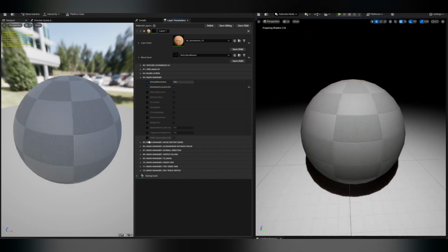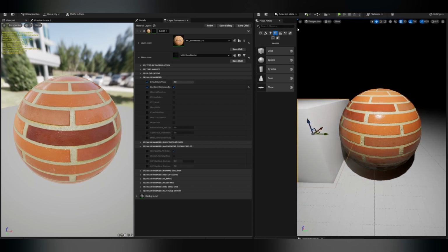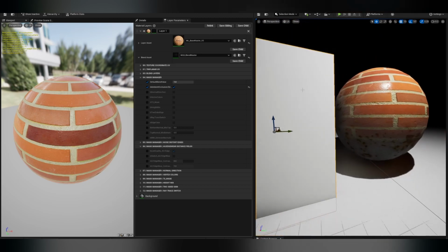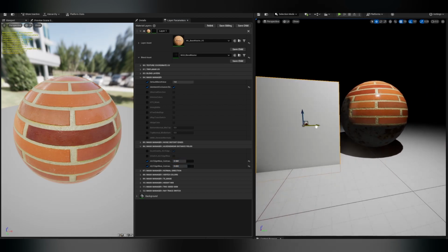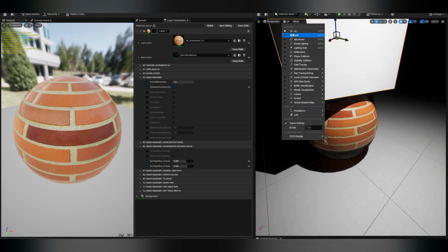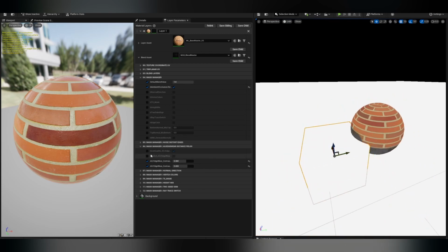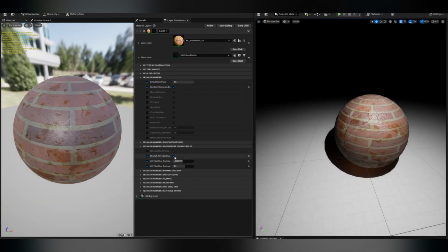Mask Manager. AO / edgewear distance fields. Enhance your material blending effects with AO and edgewear distance fields. Configure settings such as B low quality AO / edgewear and B switch AO / edgewear to control the quality and type of distance field effects. Fine-tune parameters like AO / edgewear contrast range minimum and maximum to control the fall-off, and AO / edgewear noise strength to control the influence that noise edge distort has on the final result of the mask. This effect can be very intensive, so save beforehand and consider enabling this last.